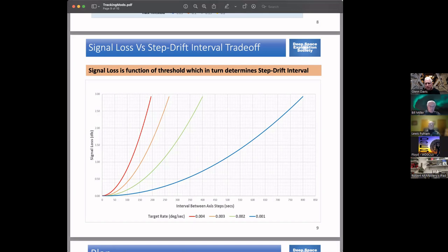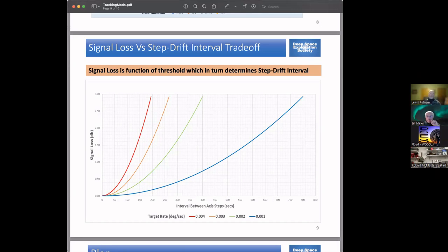So that when it ramps down, there's not a big jolt at the end when you're stopping in the tracking range. One comment, it turns out that both of the motor controllers are basically rate controllers, and they handle the ramping up and the ramping down of the rate.